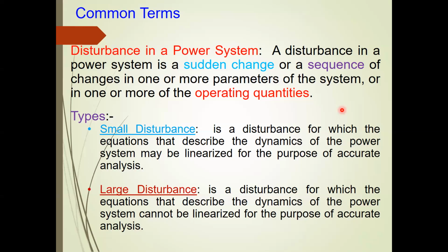This is done automatically, because normally we follow the change in the load and the change in the frequency, and then we have the use of the governors, and the governors will regulate the output power from the generator. We do that automatically.